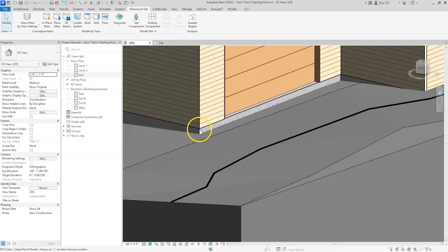Now maybe we want to bring that up a little bit closer around the front where the garage is, because we're going to put maybe a slab on there. If we're going to draw a slab right over the top of the topography, which we're going to talk about in part 2 video, we would want to run it all the way up so it's even with the top. But we're going to just keep it maybe an inch or two below the top of that slab right there. And so I need to figure out what is the elevation at that point.